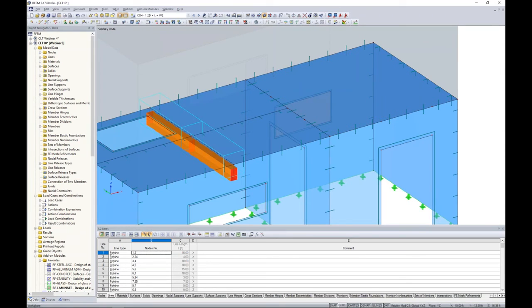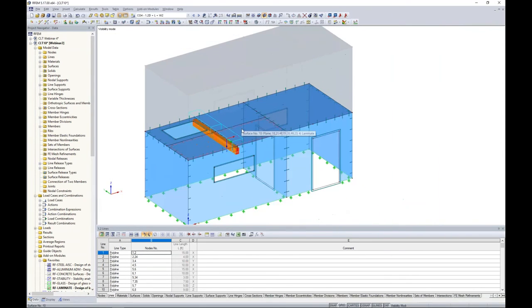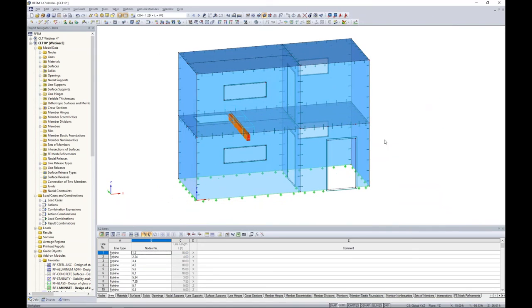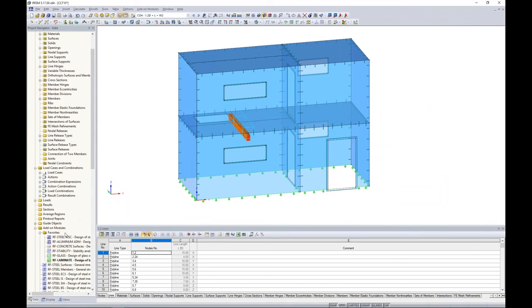Okay, so now we have completely finished the geometry of this structure. Loading, we've defined our CLT panels, so we're finally ready to run the analysis. Now, actually, one more thing I forgot. Remember within the PowerPoint, I said that we should really set the FE mesh for torsion when we're doing torsion checks approximately equal to the plank width for each individual CLT layer.